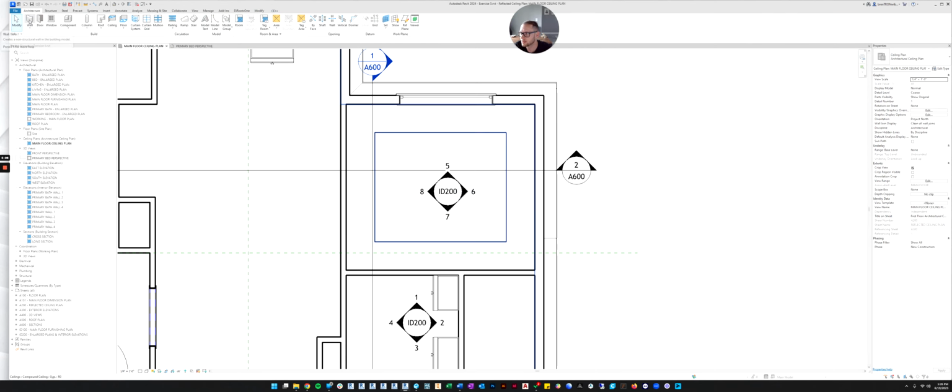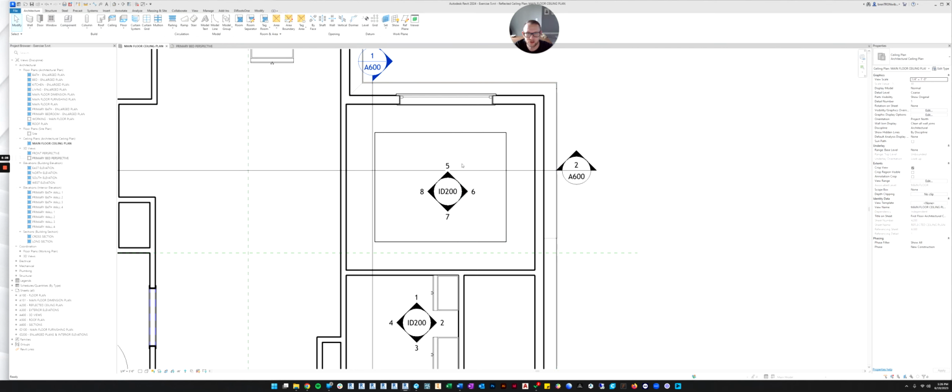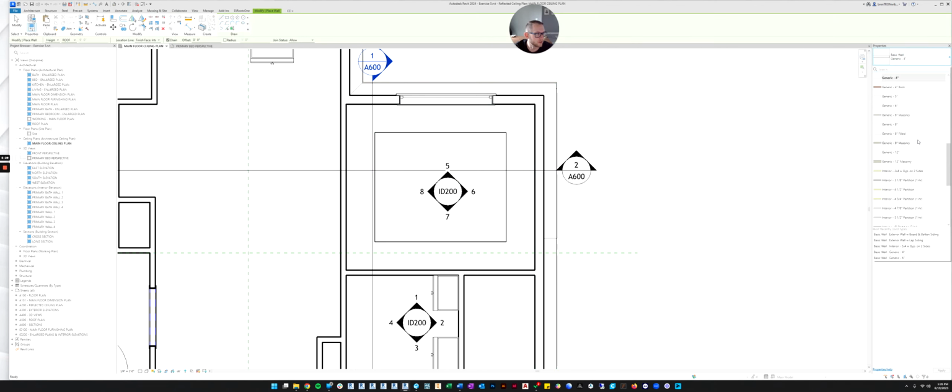The other thing I want to do is maybe create a wall real quick. Instead of our generic 4-inch, let's go to our, what did we call our walls? Let's click on this one. We called it interior 2x4. So let's select interior 2x4.